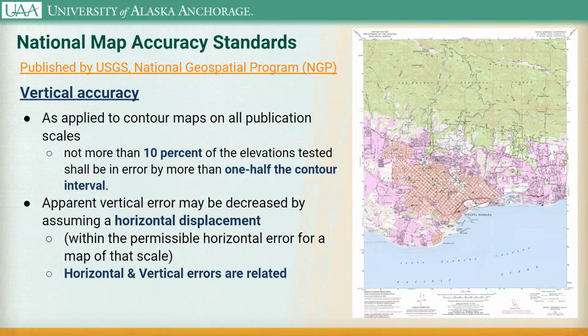And I'm going to expect a certain level of accuracy in the Z dimension, which is typically your vertical. For the vertical accuracy of a map, the way that we identify accuracy standards is based on a known elevation within a certain horizontal distance, because sometimes you can get vertical accuracy problems simply because you have a horizontal shift in your data.